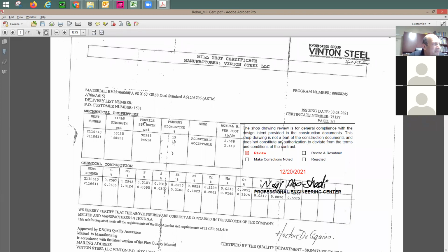If you look here, it says tensile strength is how much? This is going to be F ultimate, and look at the yield strength. It should be 60 only, but now it becomes 66,000 psi. So this is a test value. This is what you buy. It is true that in your analysis you say it's going to be 60, but most likely it's going to be higher.